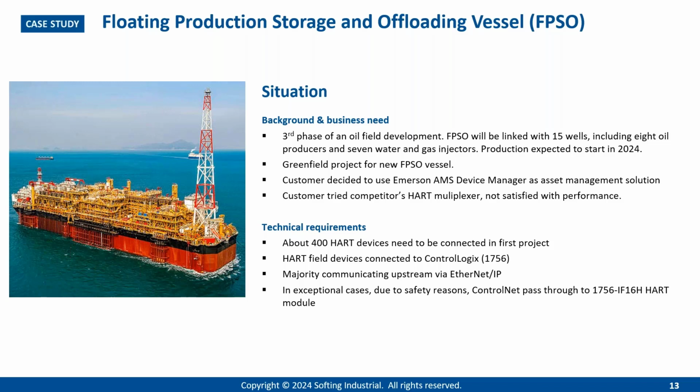And since as a first step, we need EtherNet/IP communication to Allen-Bradley systems. But if you also have in these hierarchies segments with the older ControlNet, it's possible to use that as part of this routing and then access HART devices which are connected via ControlNet to an upper layer controller. So that's transparent for our communication. Yeah, thank you. Then we can go to the next slide.